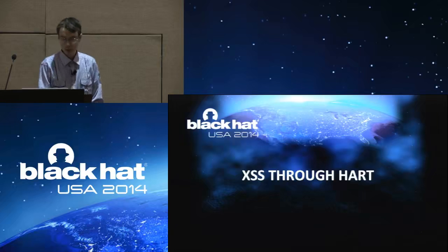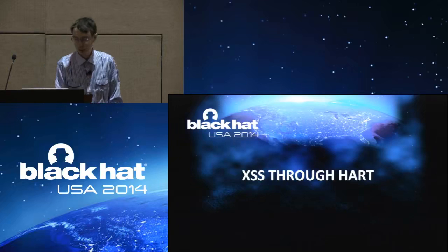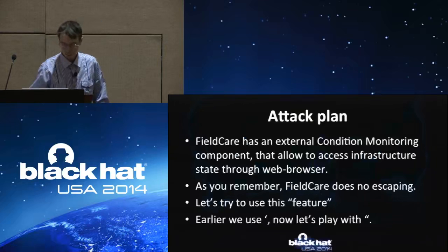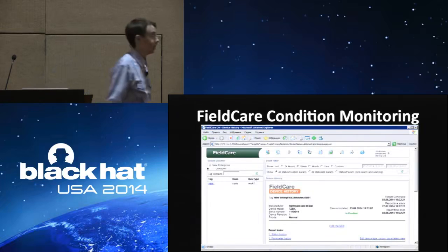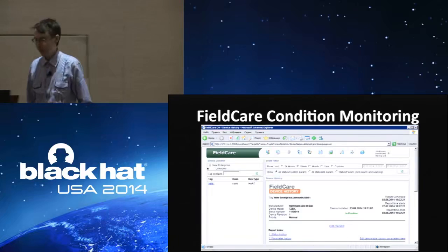Lack of filtration causes many problems, and let's see how we get XSS through HART, XSS through an analog protocol. Field care has an external condition monitoring component that allows access to the infrastructure state through a web browser. And as you remember, field care does no escaping. We know that a single quote will break the XML parser, but for an XSS attack, we can do it with double quotes. The field care condition monitoring component is shown on this slide. It looks like this.